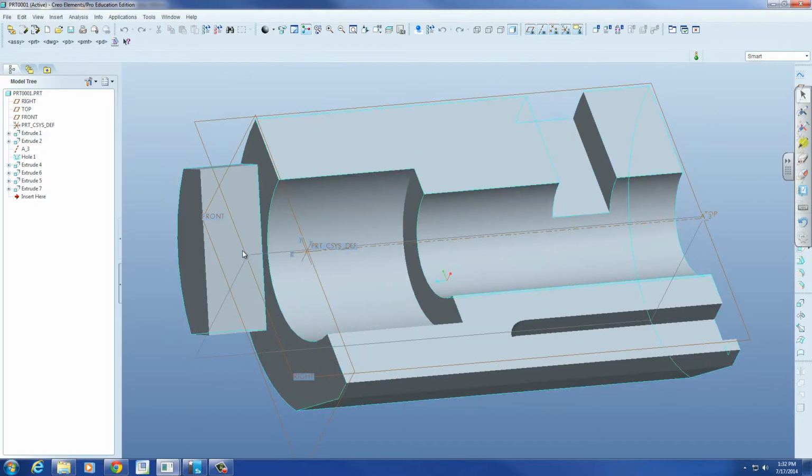So how are we going to shell these surfaces? What are the function of this? Is this surface more important than this surface? Can I pull this out from the top? You're going to have an underside here. So it may be better to pull this way with a slide after the fact. If I pull this with a slide after the fact, then I can pull most of this surface with it. Right? So we're going to look at drafting this, shelling this, leaving the top hollow.